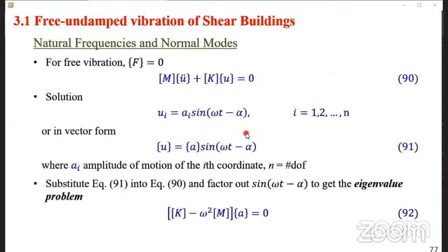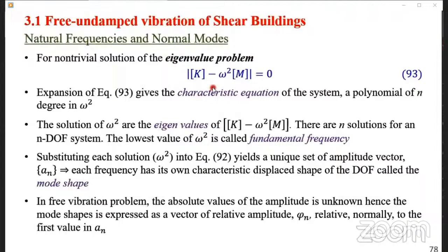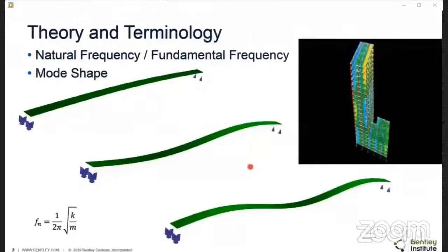Yeah, we are solving these eigenvalue problems. So we solve by getting the eigenvectors, which are the mode shapes, and then the eigenvalues that you obtain. These are the natural frequencies. And of course, the last part was explaining about the phi n. This was to ensure that we express the mode shape in unitless form. I found it important to explain further on this so that it's not just a matter of going through the course, but also understanding the physical implication of this in a real structure.